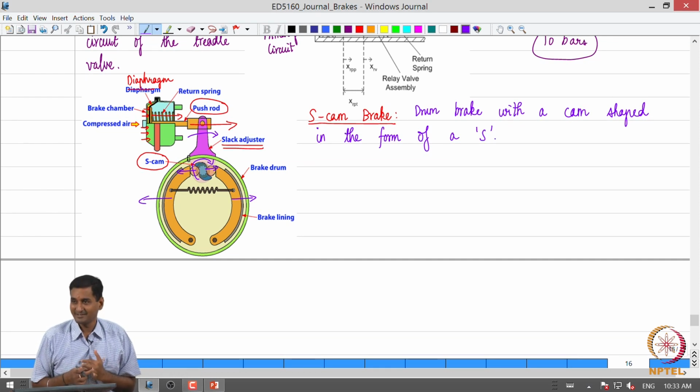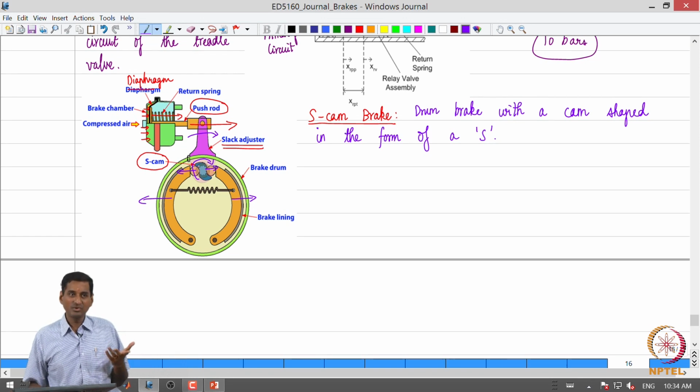Unlikely, right. So, what we may need to do is increase the actuation force. The brake factor can be adjusted, but then we need to have more actuation force to get a higher brake output, is it not? That is point number 1. Now, if I need a higher actuation force, I need a bigger actuator, and or a larger operating pressure, is it not?